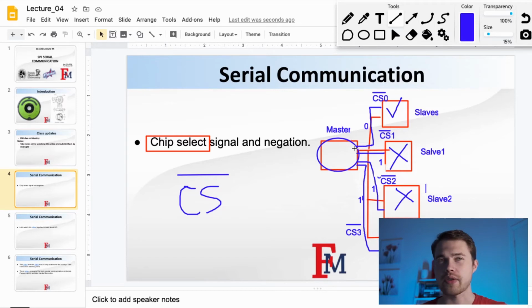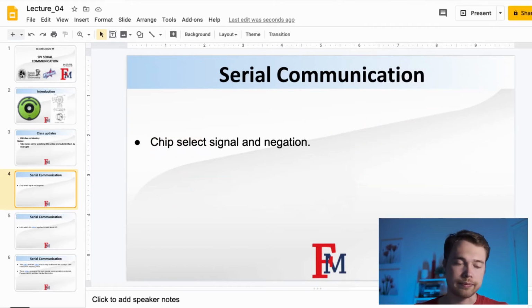Again, in UART, as far as I know, that's not possible, because it's all about two parties and how they communicate with each other. In our case, we're going to have the robot and the computer. They talk to each other, so we're going to use UART. Whenever we have a multi-device system, chip select and SPI, another protocol which we'll be talking about today, is more beneficial.